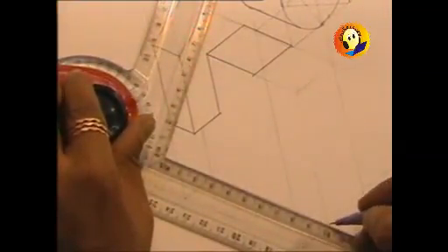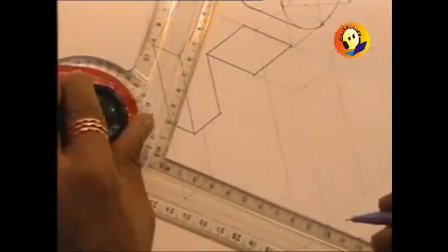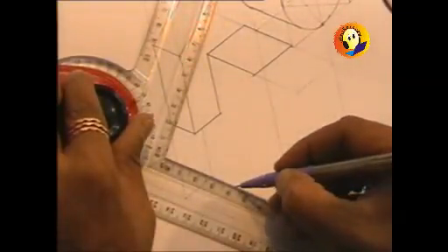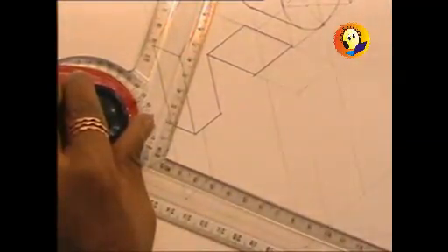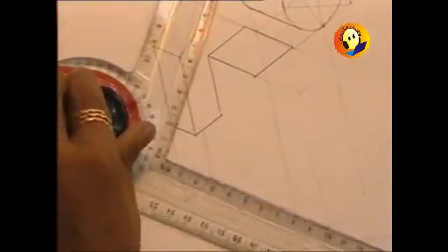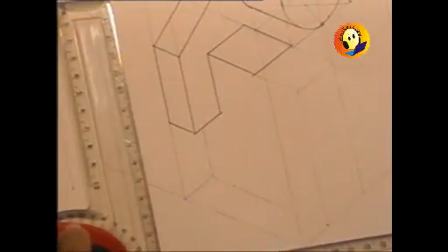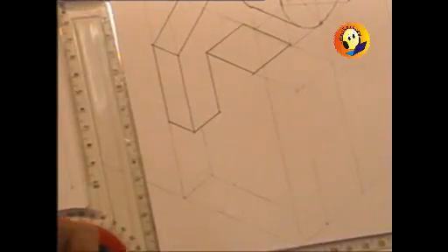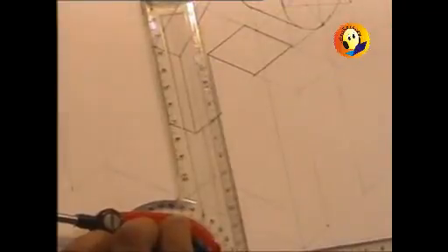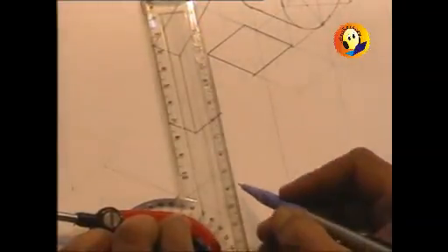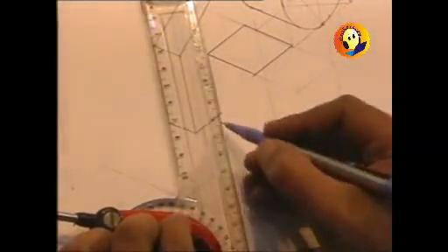Remember, even if it is some small portion of the circle to be drawn in isometric, necessarily we are required to construct the rhombus corresponding to the full circle, and then out of that only the portion can be darkened. So it is a rhombus of side 56 which is to be drawn.